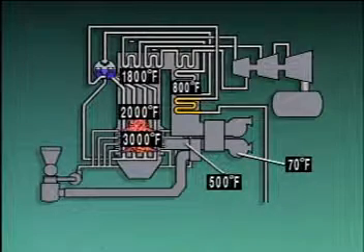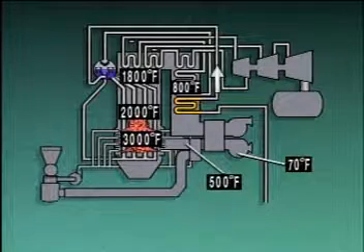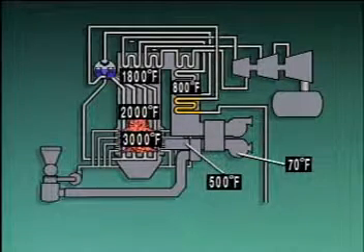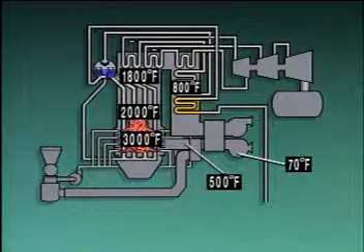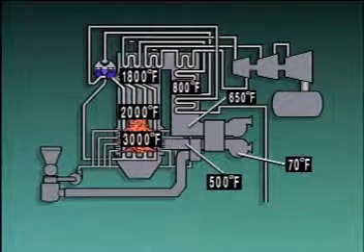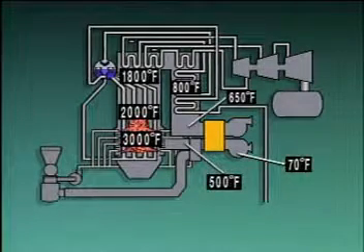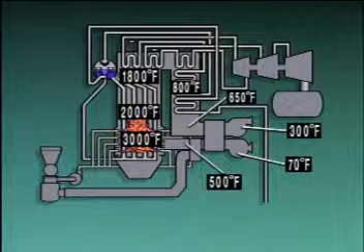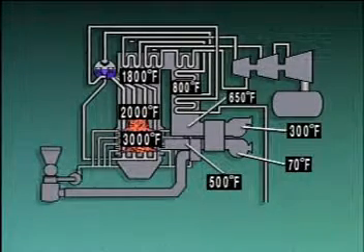economizer. The economizer uses heat from the combustion gases to raise the temperature of feed water that is on its way to the boiler. Feed water flows through the tubes of the economizer, and the combustion gases flow around the tubes. When they leave the economizer, the combustion gases have cooled to a temperature of about 650 degrees. The gases then pass through the air preheater, where their temperature drops another 350 degrees. Finally, the gases flow through an induced draft fan and leave the boiler at about 300 degrees.